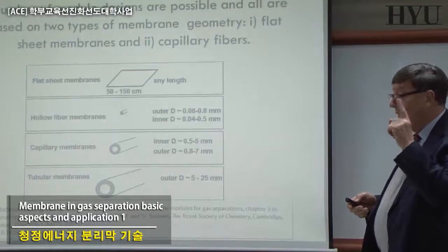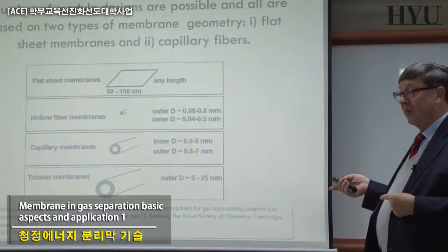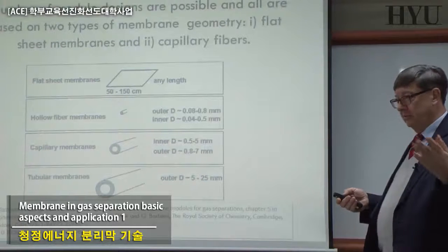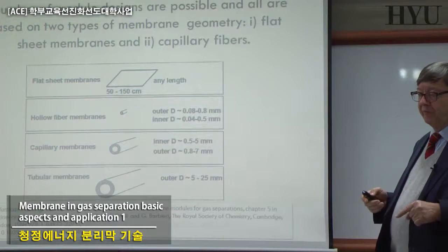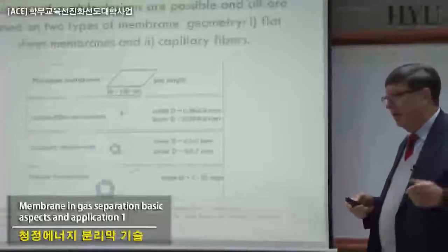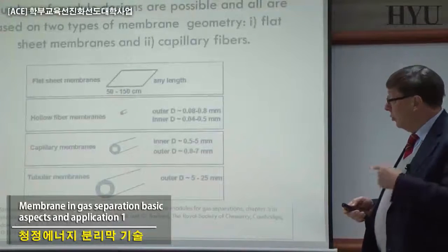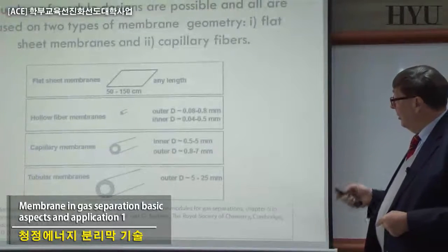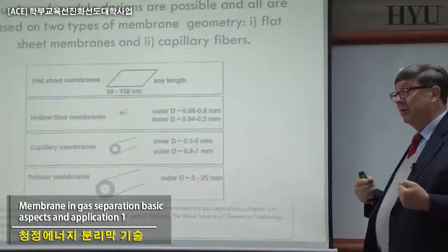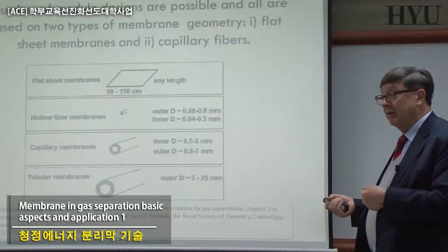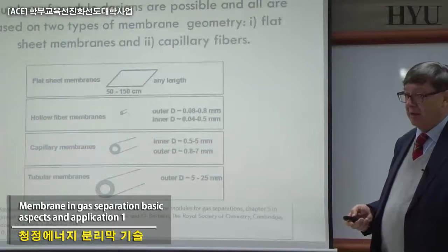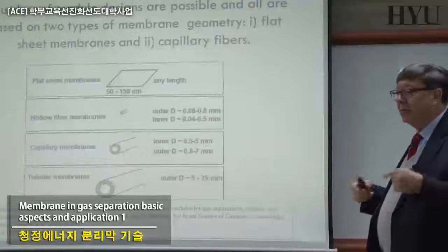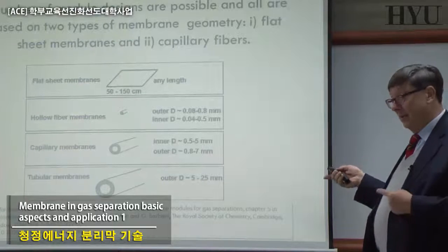Only one company today is still working in desalination with hollow fiber, and it's Toyobo, Japanese. They still are working with the traditional cellulose acetate membranes in hollow fiber configuration, basically in the Middle East, where there are some other motivations. Today, maybe some of you will start to work again with hollow fibers in desalination, because with all the new pretreatment we have been introducing in RO, that means nanofiltration, MBR, ultrafiltration, and not the traditional pretreatment of that time, maybe desalination will look again at hollow fibers.